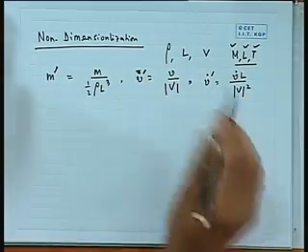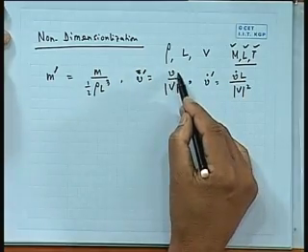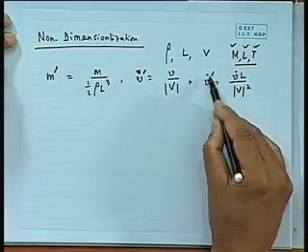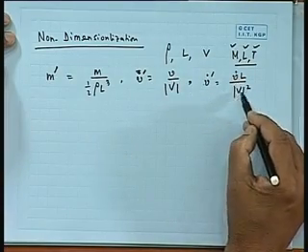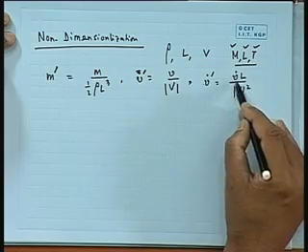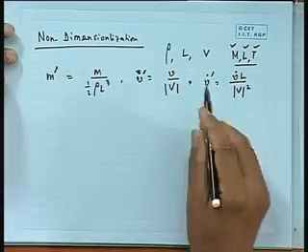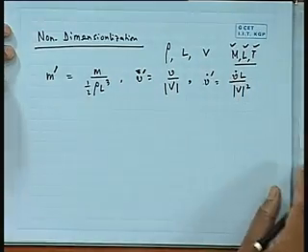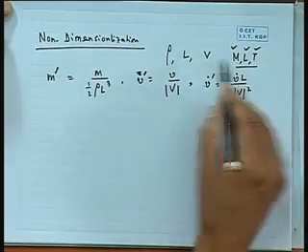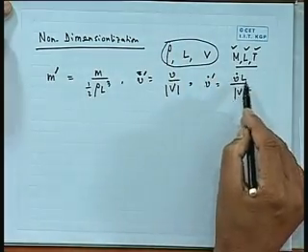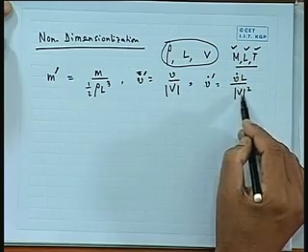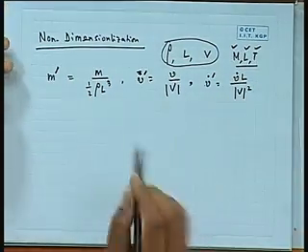See, if you see that V dash is V by V, because it is meter by second, goes away. V dot is meter by second square. So, this has a unit of, see, V dot by V into V by L, that is why it comes V dot L by V square. See, when there is a time there, then L by V square comes in. Very easily you can see, if you want to combine these three to non-dimensionalize with acceleration, it will always become acceleration by V square by L or into L by V square, something like that.